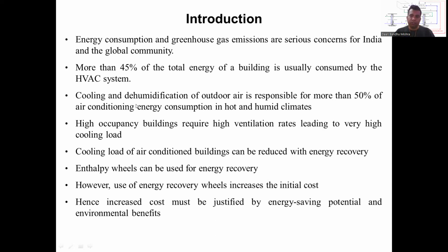energy consumption. If the building, like a classroom or auditorium, is highly occupied, then to maintain the quality of air we are required to supply a large amount of ventilation. And the outdoor air is very hot and humid, which may cause a high ventilation load, a high latent load of ventilation.